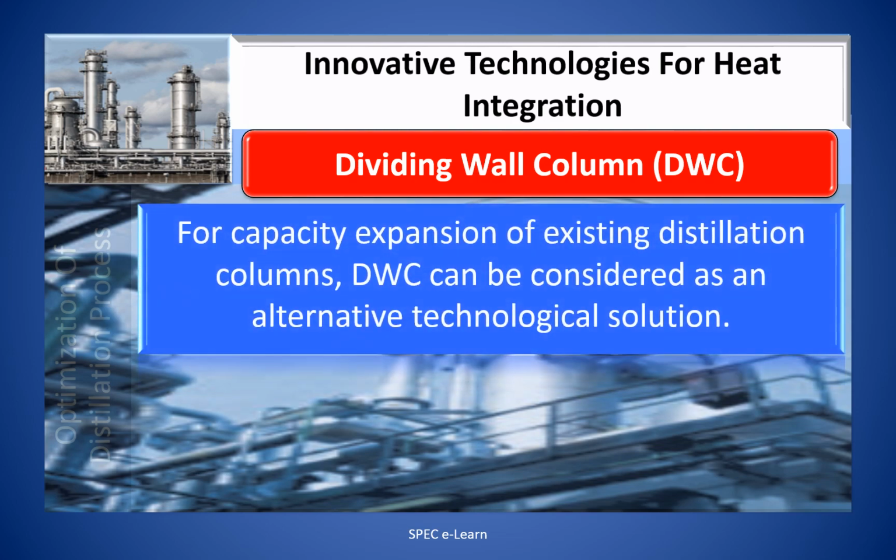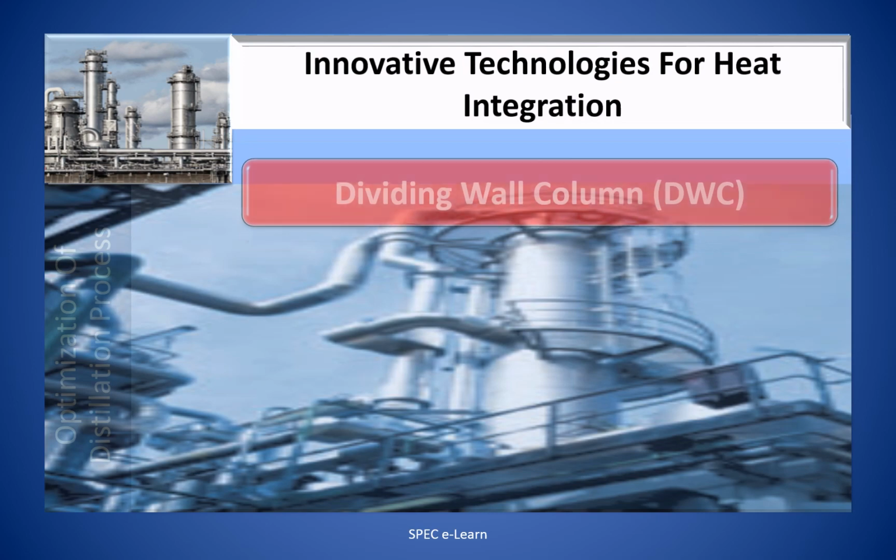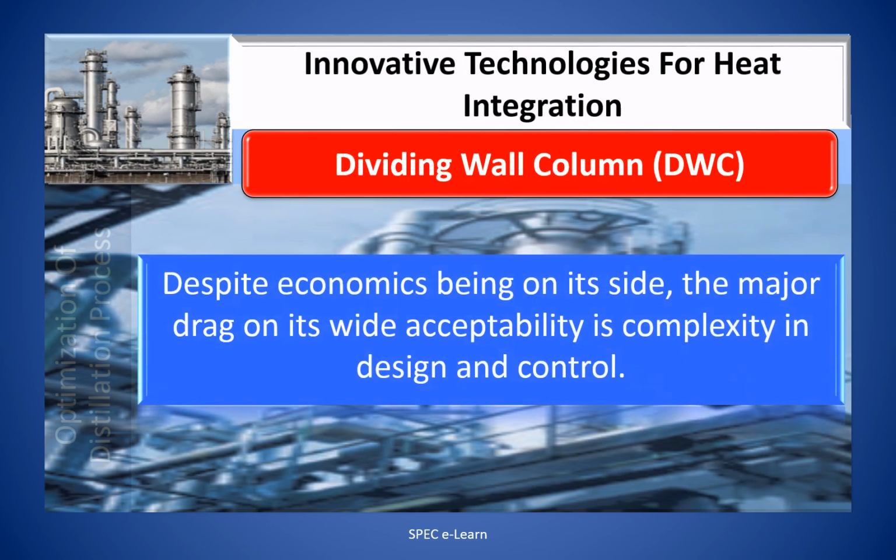For capacity expansion of existing distillation columns, DWC can be considered as an alternative technological solution. The debottlenecking of columns can be achieved with saving in capital cost and operating cost as well as higher product purity. Despite the favorable economics, the major drag on its wide acceptability in the industry is its complexity in design and control.